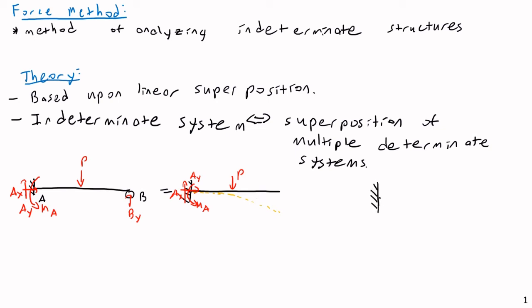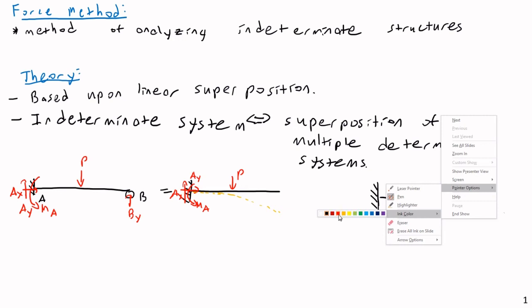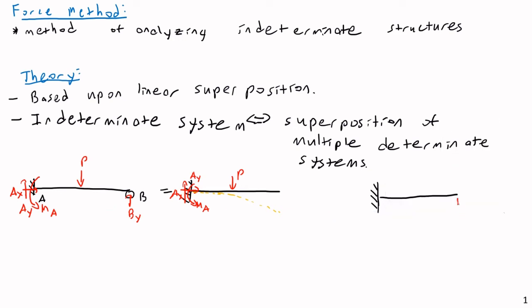With just load BY. So imagine I had a beam, the same cantilever beam, the same length, the same geometry, etc. The only difference is that the support is replaced with just a point load of magnitude equal to BY. Well, what would happen? It would deflect upward like this. Ignoring the real loads, we remove the loads that are actually on the structure, and say how does this deflect under a point load equivalent to the load in this roller here.